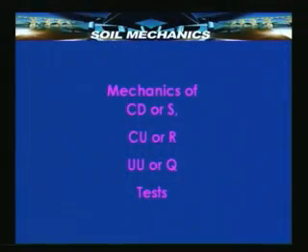Now, let us see the mechanics of these tests, and unless we understand the mechanism involved in this test, how the stresses are changing, we will never be able to understand what kind of shear strength parameters we are getting from these tests. Are we getting total stress parameters? Are we getting effective strength parameters? If we are getting the total strength parameters, how to get the effective strength parameters from them, and so on.